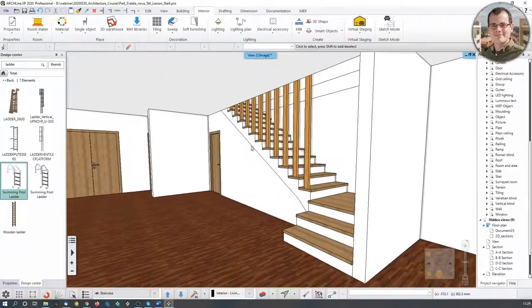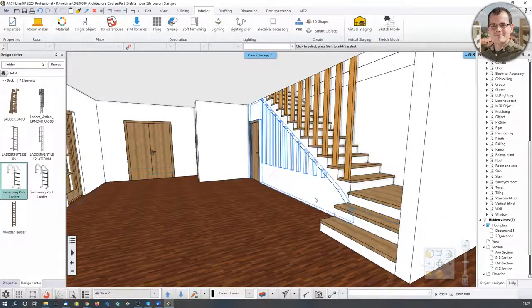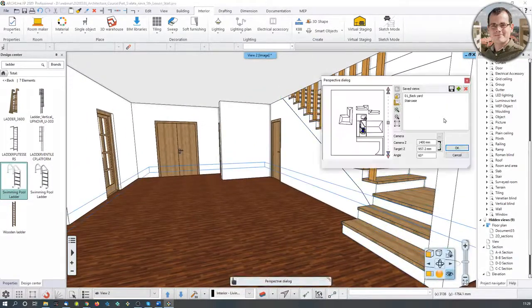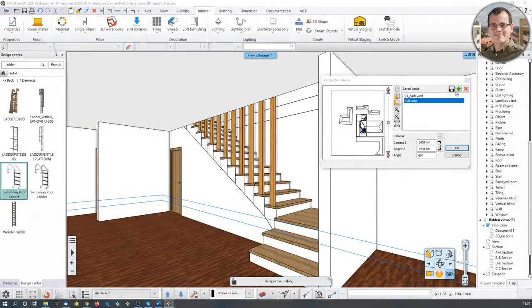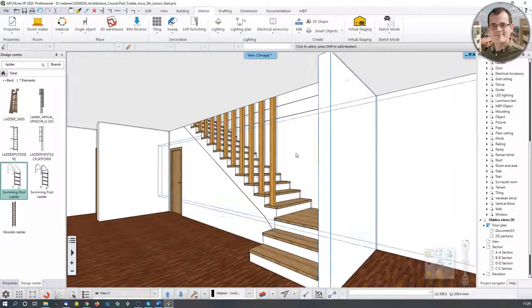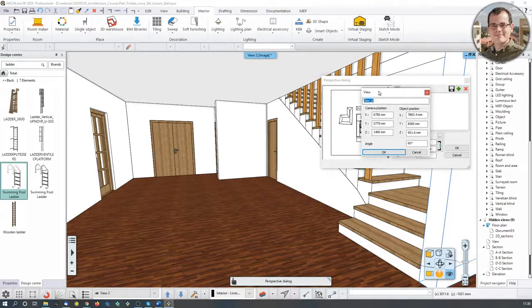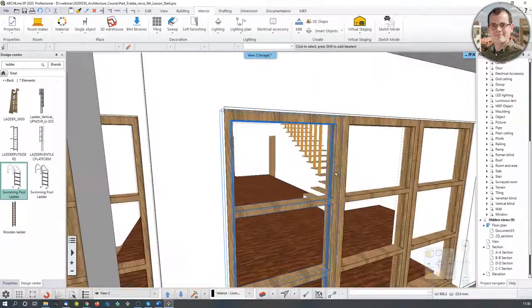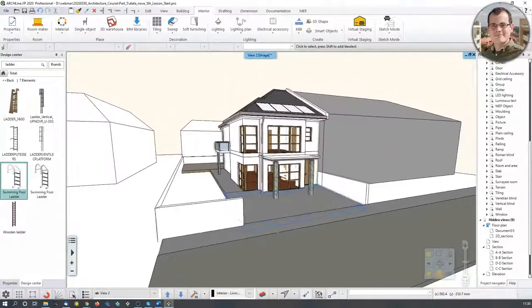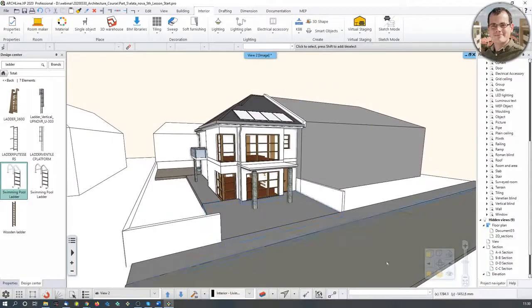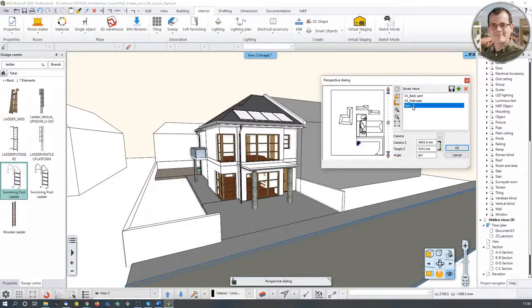This view we have set up before, but now I'm moving it a little bit, and I want to override this. So I don't want it to revert to this view. I want to move it like this. So I'm just going to go to the plus icon and hit save. And let me just, I think I'm just going to discard this, and just going to do this, eye icon plus, that is going to be 02 staircase, and I want to have another one which is on the outside, so I'm just going to do it like this. And especially here it would be nice to have an overview, so something which is maybe a bit higher, like this. That is going to be 03